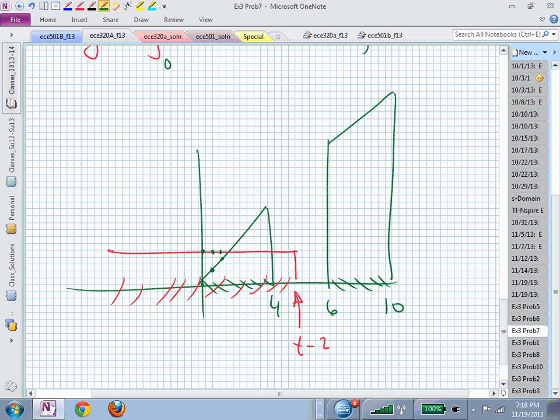The other thing that you need to realize is that convolution is continuous. If you now have an interval of y that stops at 4, and then another one that starts at 4, if you evaluate the waveform y of t at 4 in both of those overlap patterns, you better get the same number. Did that make sense?